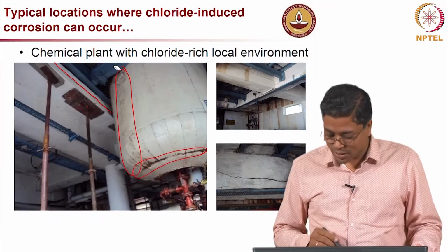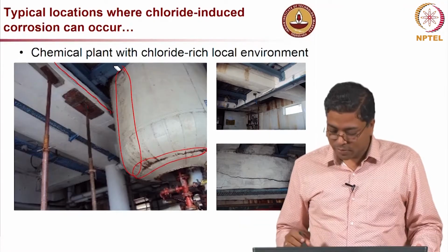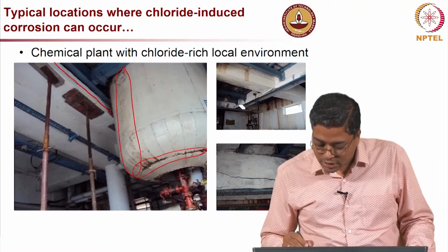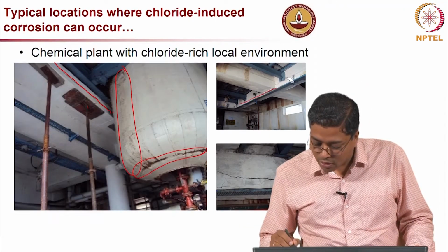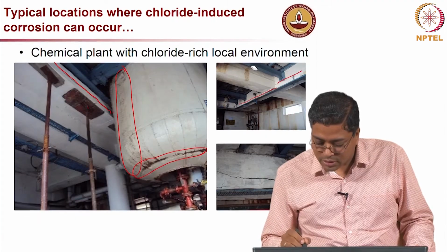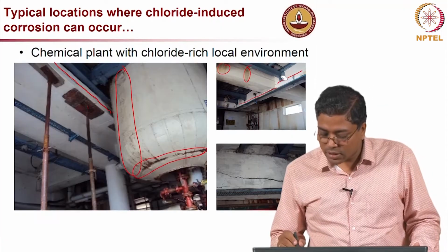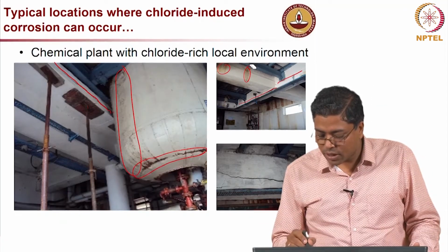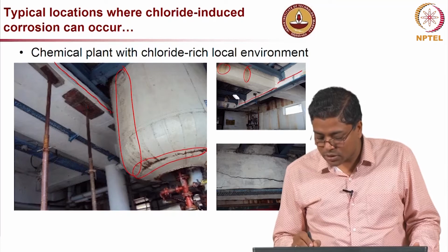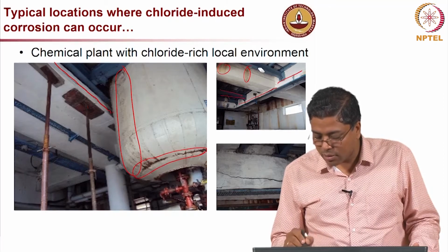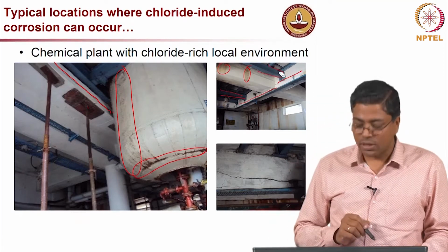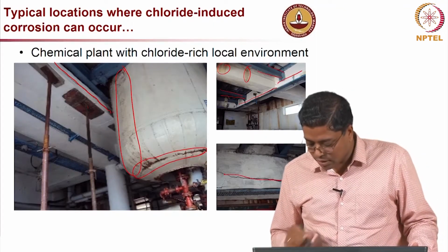So, that is something which we have to stop. And here also you can see a lot of cracks all along the structural elements. There are a lot of signs of corrosion, and you can see that they have also tried to do repair work, installing some steel elements, structural steel sections over there, with severe cracking through the beams.